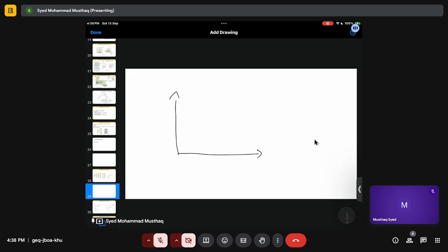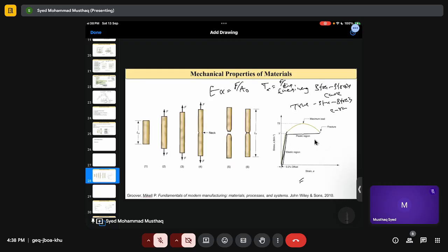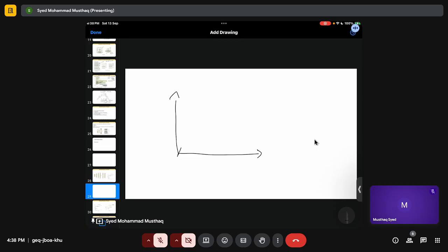So yeah, I have prepared my tensile sample and put it in a tensile testing machine and it starts stretching it. At first my sample will behave like an elastic rubber. If you stretch an elastic rubber, it will regain its original position. The same goes here. If I apply stress, it will elongate, and if I remove stress, it will come back to its initial position. If I apply more stress, it will elongate even more, and if I remove stress, it will again come back to the same position. So more like a rubber band.